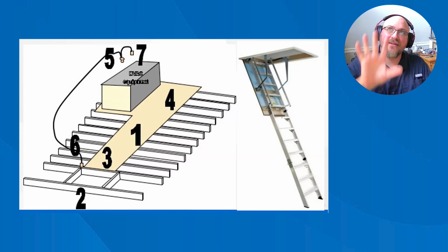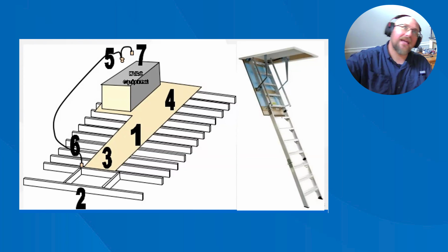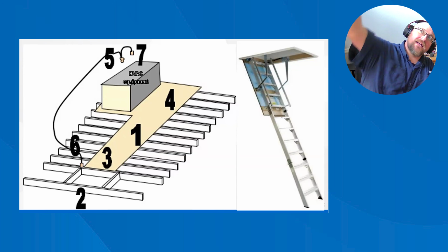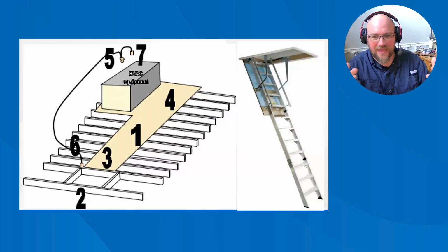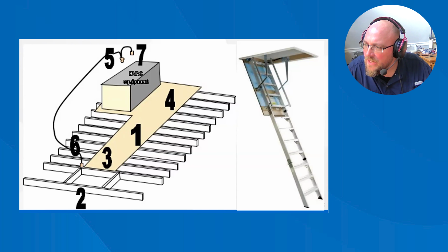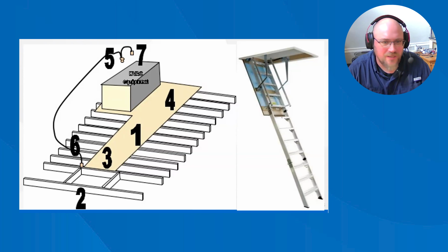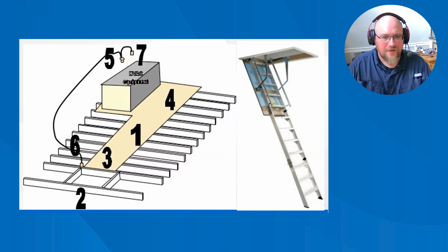Same thing goes when you have an attic hatch. I try to not be directly underneath the attic hatch. I try to keep my head off to the side and then push up and over because anything that is on or around that attic hatch, you'll get a face full of that stuff, and it's nasty. Especially in older existing homes. Cracked steps, you'll see that a lot, especially if the attic stairs were not installed correctly. They're overextending, or the feet are not cut to the slope of the floor.